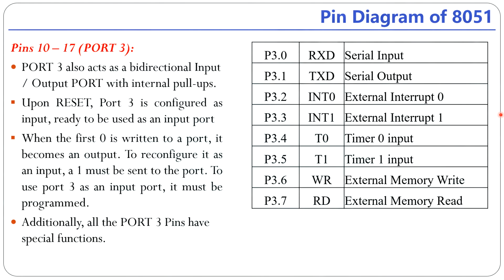We can see here port 3 basically. The first pin, P3.0, represents RxD, the serial input, we can say the receive data. P3.1 is the transmit data, serial output. P3.2 is INT0, the external interrupt 0.